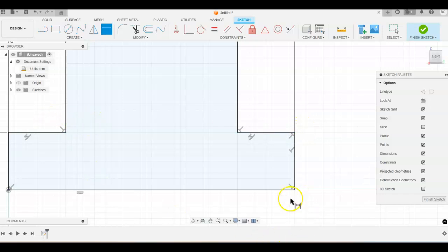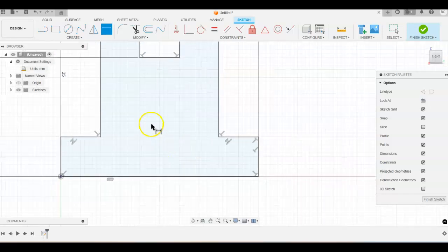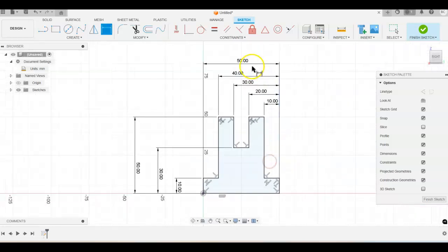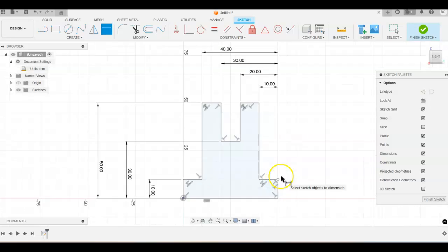My extension lines look like they're connected. Well, why are they connected? Because it's really going down to this line. So there is a little gap in the extension line. We can't see it because we've got our object line here. When we do these drawings, remember the standard requires a gap between the extension line and the border line. So the better way to do this, let's delete that out, is to select from this line over to that line and place that. That way we get that extension line in there all the time.